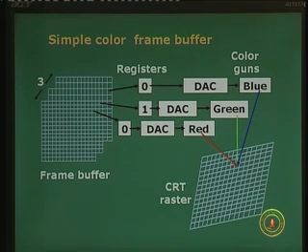So, if you look into the screen now, there are 3 such bit planes, and we assume here that the corresponding bit values, 0 or 1 only in this case, are taken out from the frame buffer, loaded onto a 1 bit register, which in fact fires a DAC. The digital to analog converter will convert that bit value into a corresponding voltage, 0 or some non-zero value, for the corresponding color guns. We have been talking about 1 color gun so far. Now, for the first time we are going to have 3 color guns separately for the 3 colors or 3 channels.